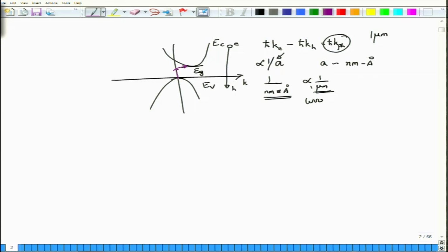side. So you can see that there is one vertical transition line, and then to make the further transition onto the conduction band, you need to have a phonon, not a photon but a phonon, which is the material's quantized particle. Don't worry about what that is, it's just something in the material that has to assist the photon.